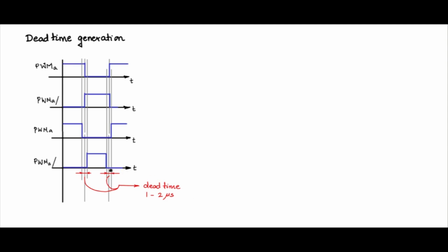So how do we implement that? Normally, if you take the PWM generation scheme, you have VM, that is the modulating signal, which is the low frequency sine wave. VC, which is the carrier signal, is the high frequency triangular carrier, compared in this fashion, plus and minus, and you get the PWM output. And that PWM A is inverted, and you will get PWM A bar. So this is the normal way of generating as we discussed.